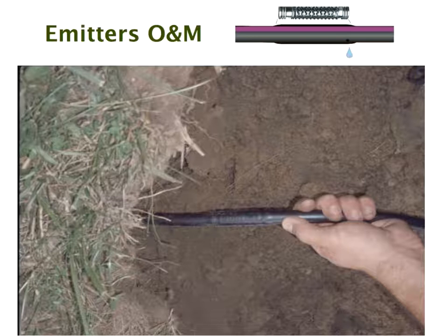Now, even though there is an antibacterial in the dripper, as I mentioned yesterday, ours is tributyl tin maleate, and our competitor's is an arsenic compound, and it certainly does a lot to prevent the biological mat. But if you put enough through, it's going to just plug it up with dead bacteria.